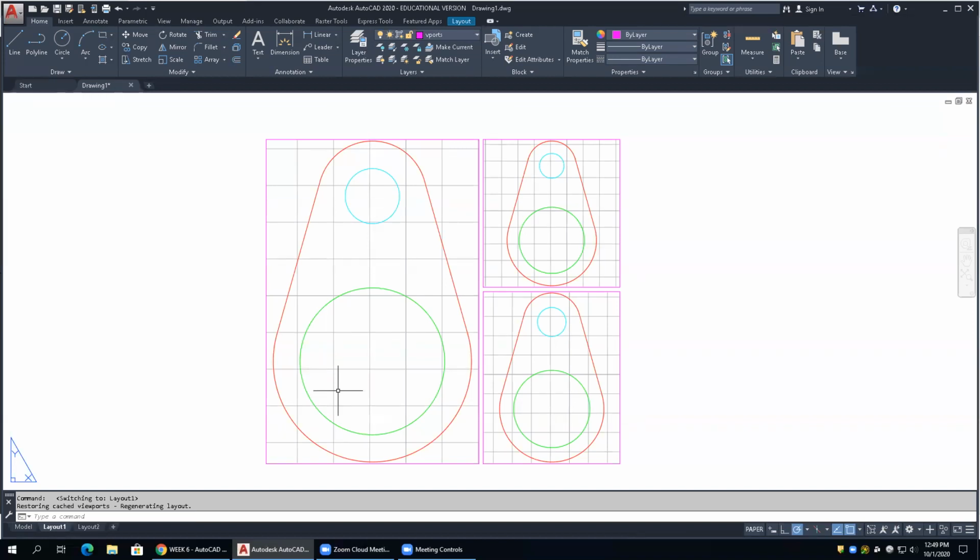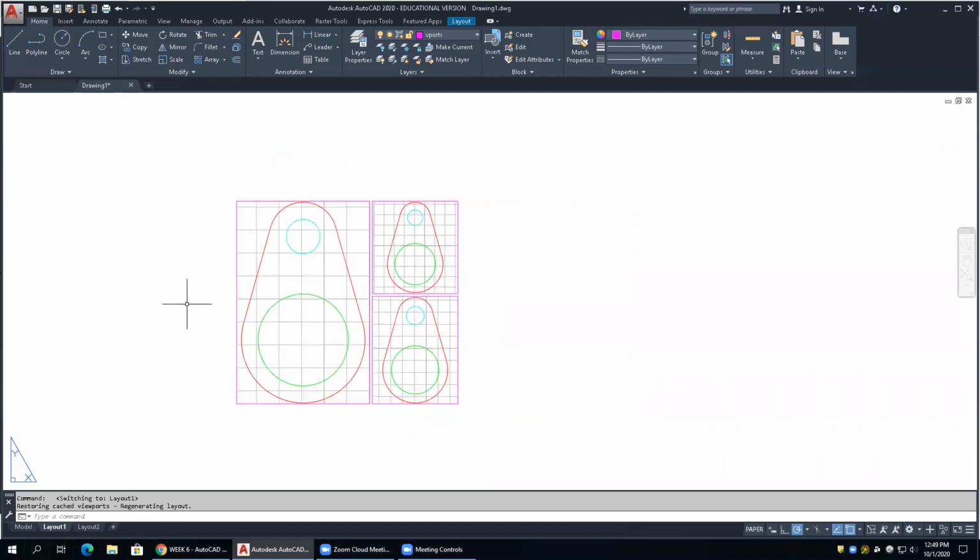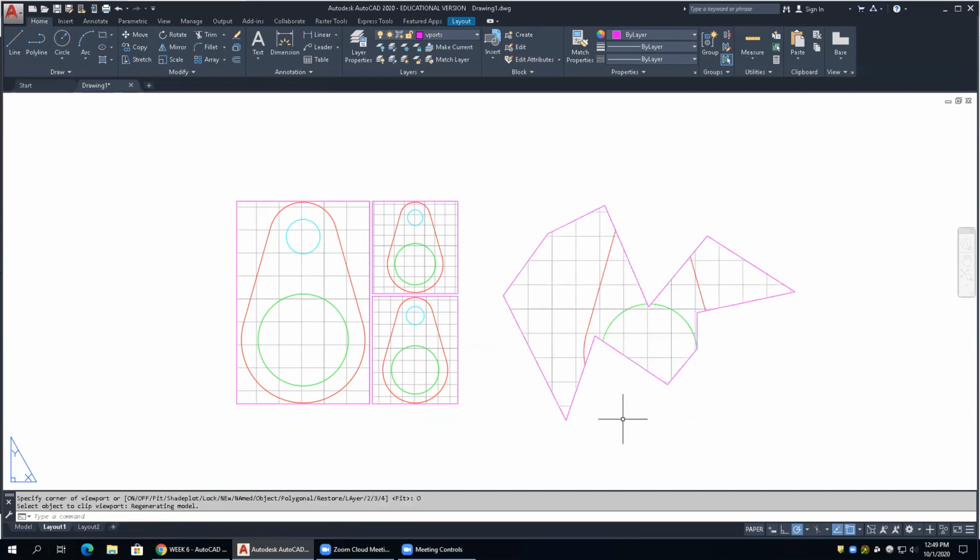Well, I'm going to show you something here. Watch. You guys don't need to do this, but I can go in and create a really outrageous polyline like this. And then go into mview and turn that into a viewport. You notice what I just did? So it's impossible for me to do that with tiled viewports. And you might think, well, why would I want to do something like that? And there are reasons, okay? I do irregular shaped viewports a lot, okay?